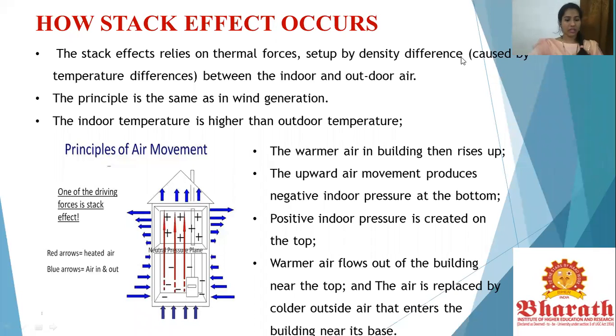So to understand how exactly the stack effect occurs, let's look into detail. The stack effect relies on the thermal forces set up by density differences. These are caused by the temperature differences between your indoor and your outdoor air. The principle is the same as in wind generation. When the indoor temperature is higher than the outdoor temperature, the warmer air in the building rises. The upward air movement produces a negative indoor pressure at the bottom, and thereby a positive indoor pressure is created at the top. So the warmer air flows out of the building near the top, and it is replaced by colder outside air that enters the building towards the base.